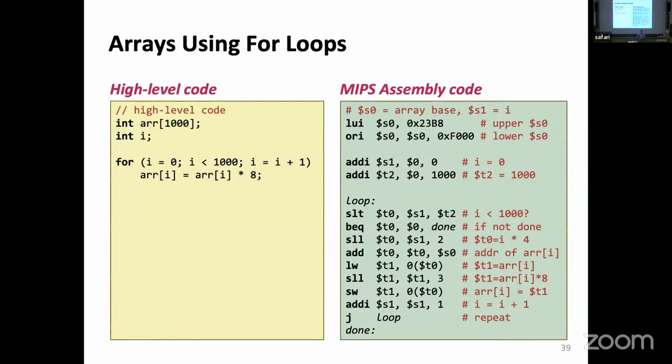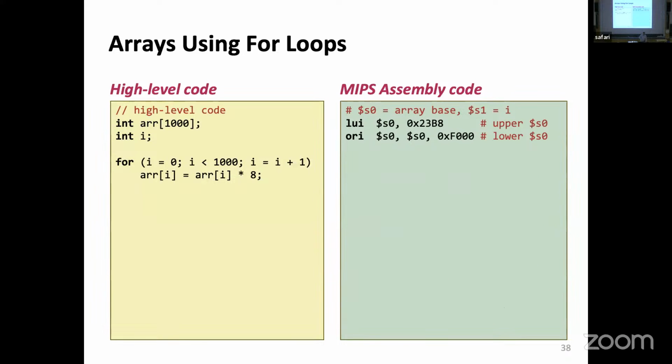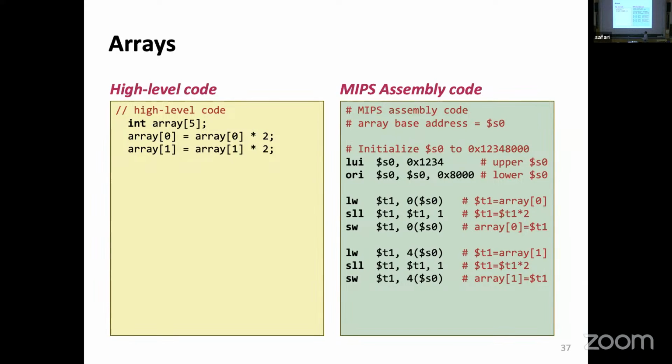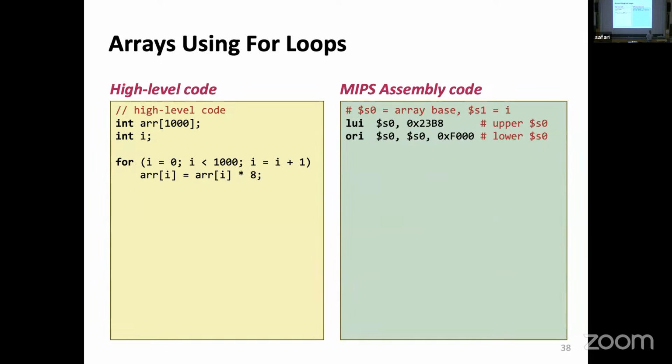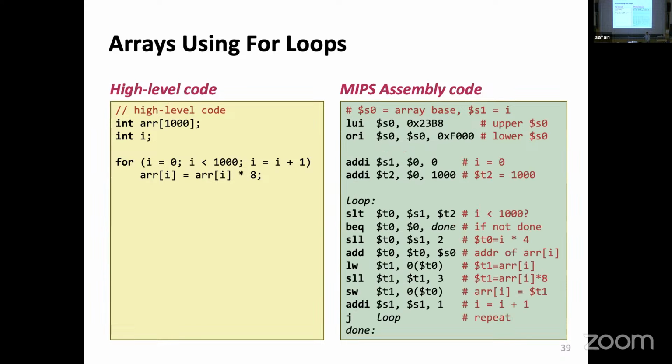So from something where things were very simple and not like a program that we would be writing, it's actually the same trick. We combine the two tricks that we had before, the for loop and the array addressing, and all of a sudden we realize that these are the things that are happening, and if this takes 1 nanosecond, 1, 2, 3, 4, 5, 6, 7, 8, 9 nanoseconds are needed to make one loop, right?